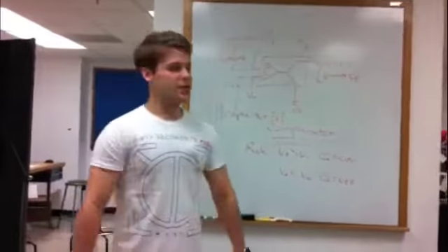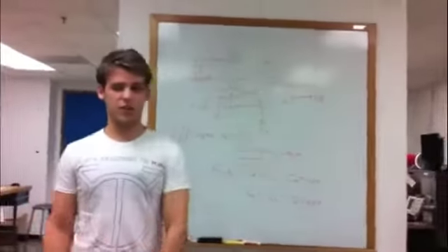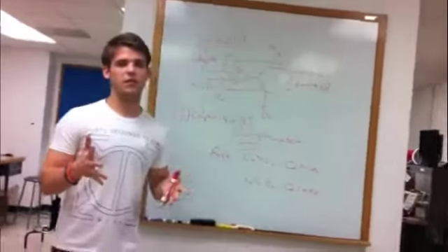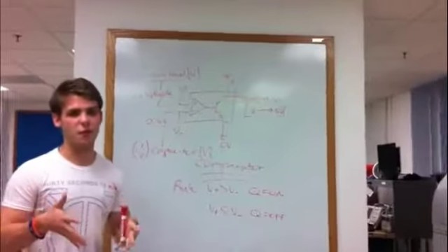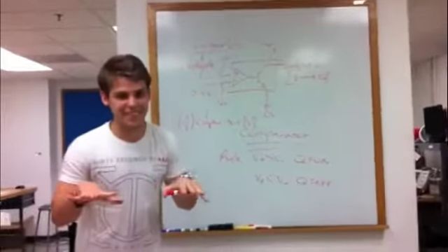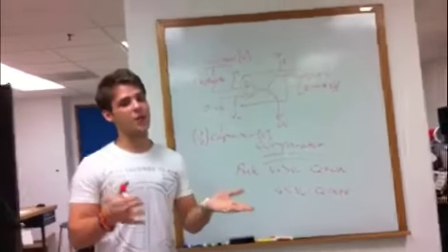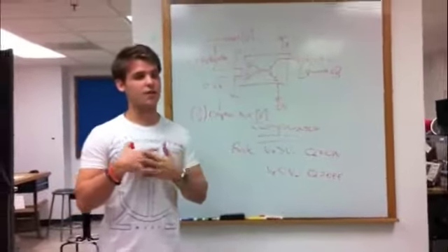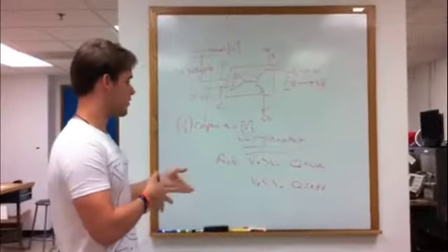When the solar panel is removed, i.e. during nighttime, the discharging capacitor is responsible for powering both the illumination circuit and the charge monitoring circuit with the remaining power. The purpose of our first circuit, the charging circuit, is that we want the solar panel to charge our capacitor up to 5 volts, but then we want it to autonomously stop. But there's a problem because our solar panel has 9 volts, so we have to find a way for it to stop charging once it hits 5.